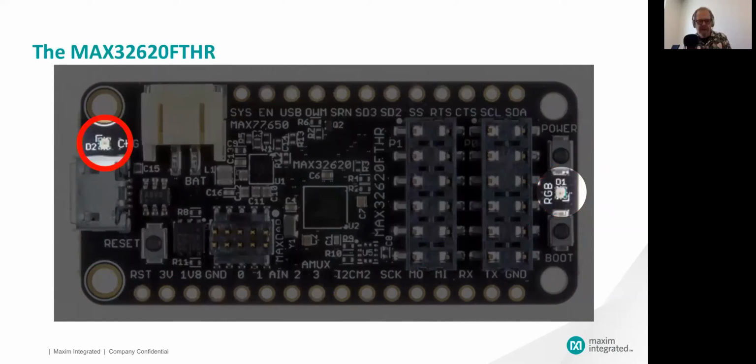But over on the left-hand side of the board, there's a LED that's connected to the PMIC. The PMIC has current drivers specifically to drive an LED. And that means 2 things, really. First of all, it's not connected to just GPIO pins. So you can't just go to that LED and directly turn on a light. You have to ask the PMIC nicely. But the cool thing is that the PMIC itself can modulate the current through the LED. So you have brightness control, and you can change the color to pretty much anything you want.